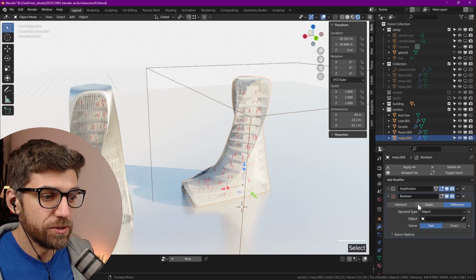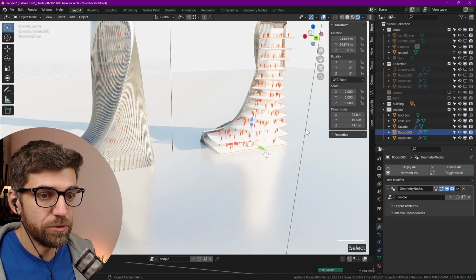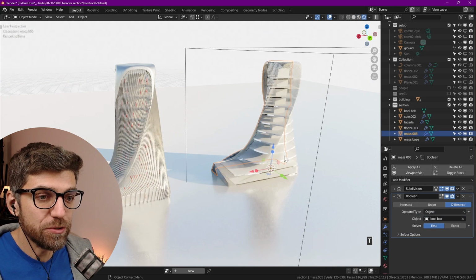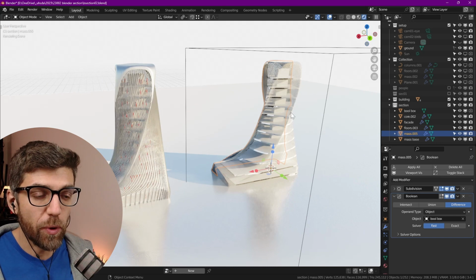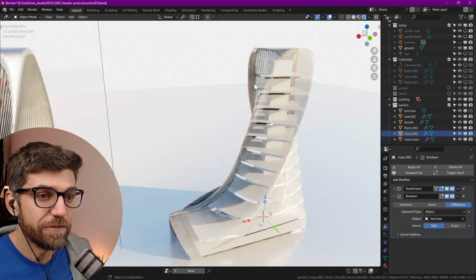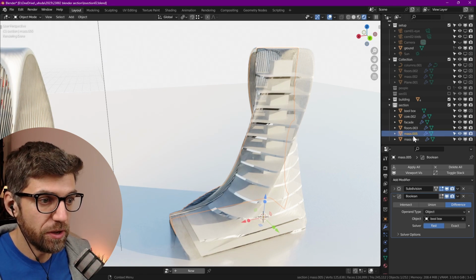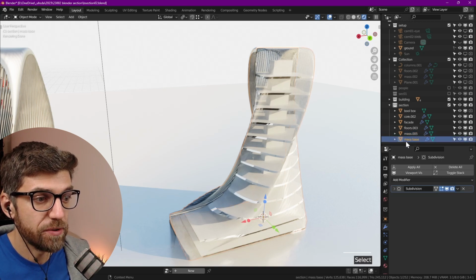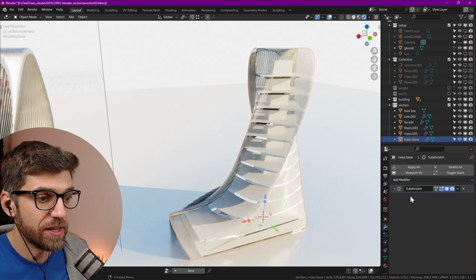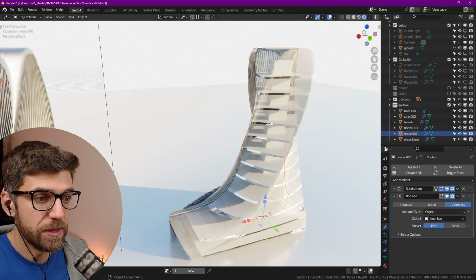Next, let's click on mass 005, click on bool box, difference, and now we are missing all the massing. And let's continue now with our floors. So to make this work, we actually need to duplicate our massing. The reason for that is that we'll boolean one of the massings, but we need to keep one intact so we can first get the right footprint of all of our floors. So I've duplicated it, so mass 005 is the same as mass base, and I renamed this one mass base. It has subdivision, but it doesn't have a boolean modifier, whereas mass.005, that one has the boolean modifier. That's the one that we see cut away with the box.